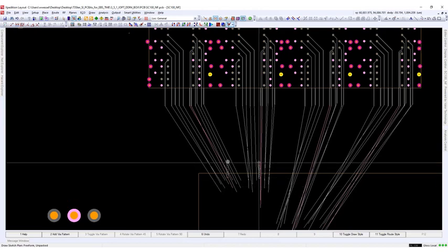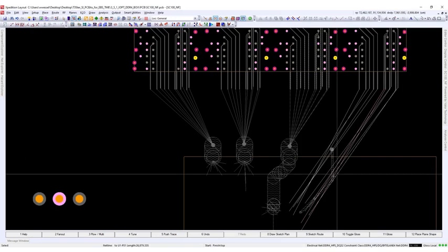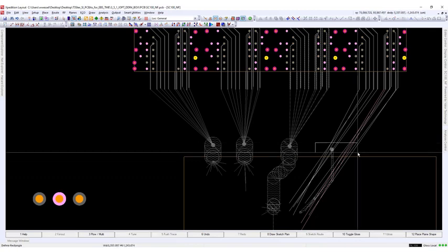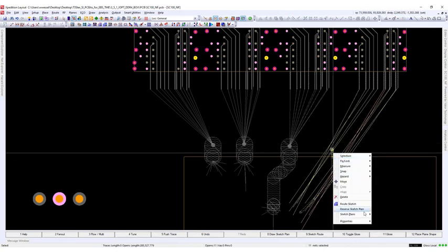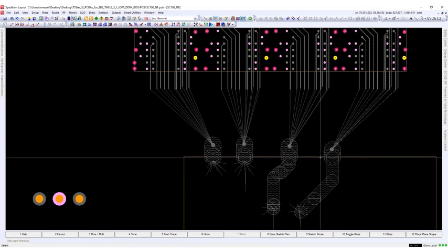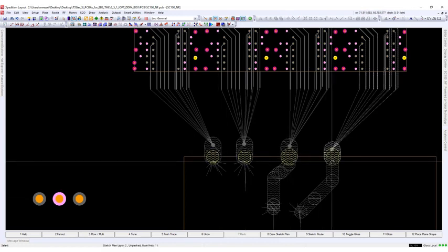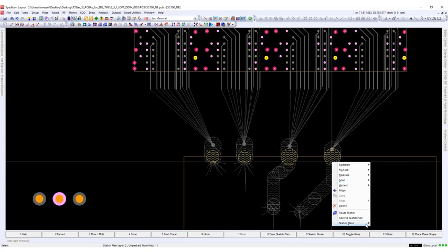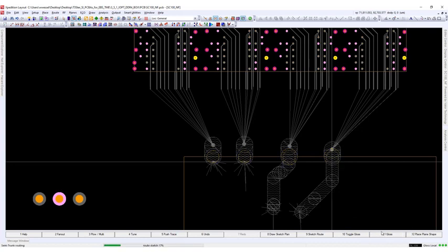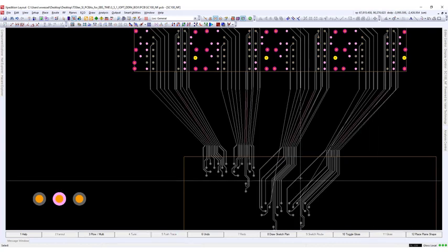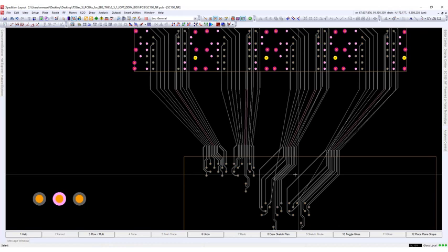On layer 2, 4 sketch plans are placed, and the netlines from each byte lane are added to the corresponding sketch plan. Semi-trunk is used to finish the routing. We see that it automatically adds wires and the breakouts. In comparison to manual routing, this is an enormous time saver.